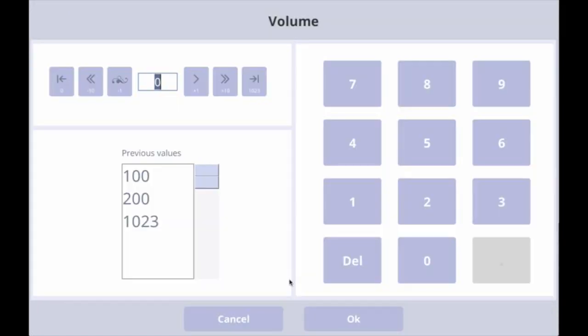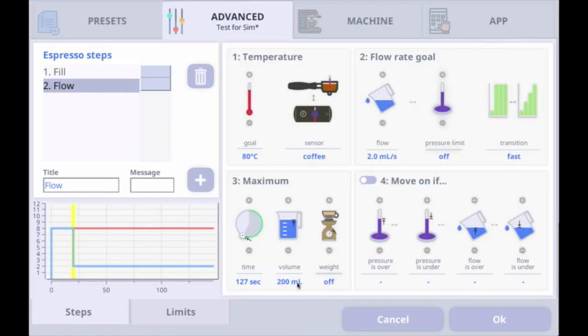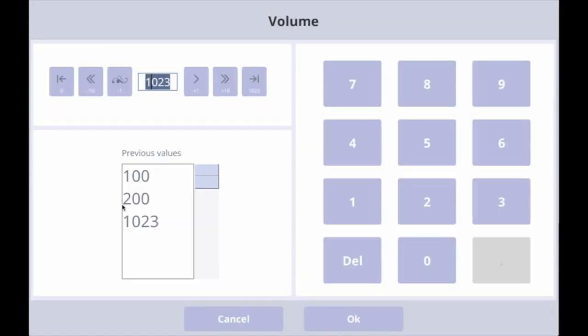Again, we need a positive value for the volume. In this case, I'm going to set it to max. I know we're not going to pump more than 200 mils, and if we are, there's something wrong. If I set it at 200 mils, it means if something happens, I collapse, or the phone rings, or I get distracted or whatever, I know the profile's not going to pump out a litre of water and overflow onto the bench or ground. So if I set 200 mils, it just works as a prevention if something goes wrong. So I'll set that at 200 as well.